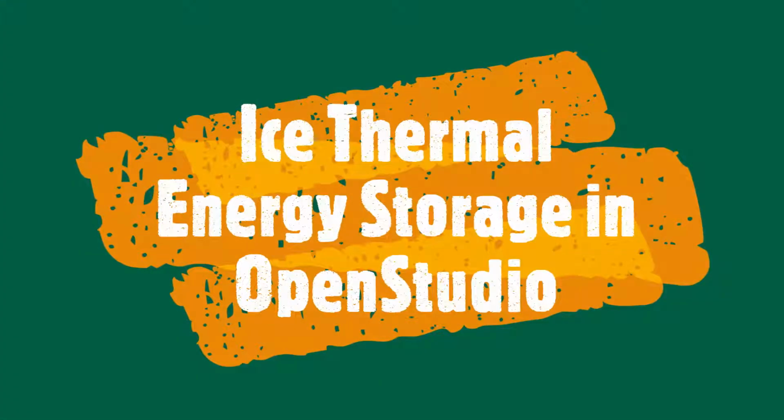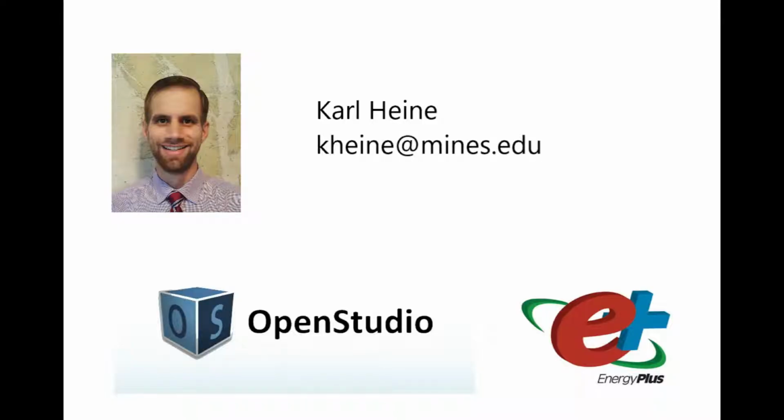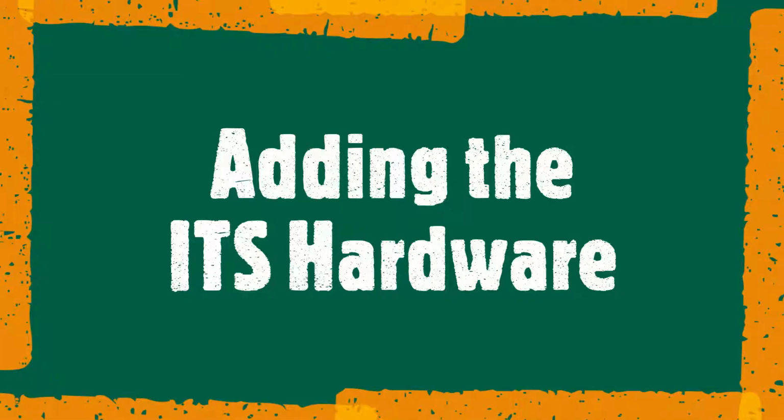Hello and welcome to the how-to guide for adding ice thermal energy storage to OpenStudio. My name is Carl Heine and I'll be walking you through the steps to add the ice storage tank and get it working in your OpenStudio model. Before we begin, you need to make sure that you have a working building model with a chilled water loop.